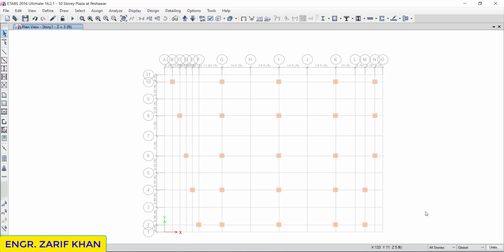This is actually 10 stories, so it will be a raft automatically. So all these columns will be connected in the raft. Just provide a beam here to connect all these columns, as this will help us reduce our lateral forces and the demand as well. It will be very good if we provide the beam on the bottom floor as well.